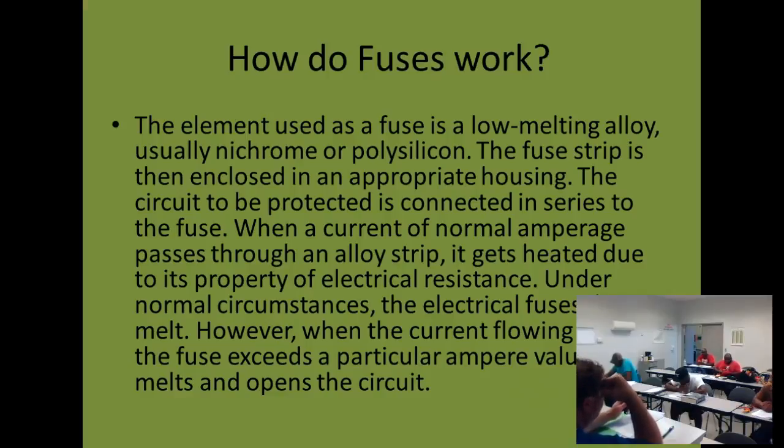I wouldn't recommend you grabbing it. But there's voltage there, and your meter won't read it. The voltmeters we use, these multimeters, are made to read a difference in voltage, not the presence of voltage. You can get an oscilloscope and several other different things, but these read a difference in voltage.